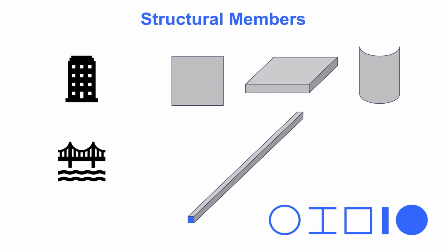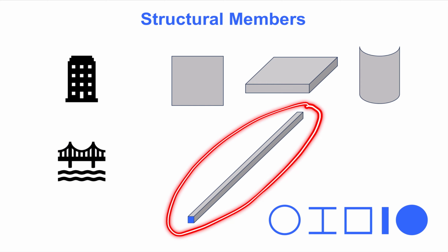An important choice when employing truss, beam, and frame members is the type and dimensions of the cross-section. Circular, wide flange, and rectangular cross-sections are available. Furthermore, for the so-called thin-walled cross-sections, they can be either open or closed. More details about cross-section analysis are provided in a short course on cross-section analysis posted at terje's Toolbox. That is because we can often separate the analysis of the member from the analysis of its cross-section. It is the analysis of the full member that is the subject of the present course.